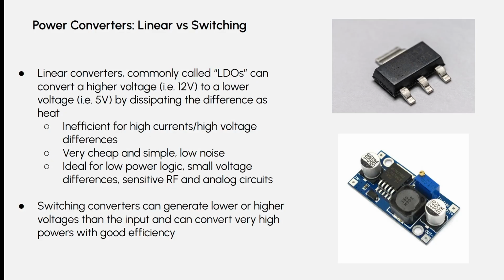On the flight system for the rocket, this is most apparent by the fact that we have a battery on board, which is not only a somewhat random voltage, but a random voltage that changes over time as a battery discharges. It can change up to like 25% throughout its discharge range.